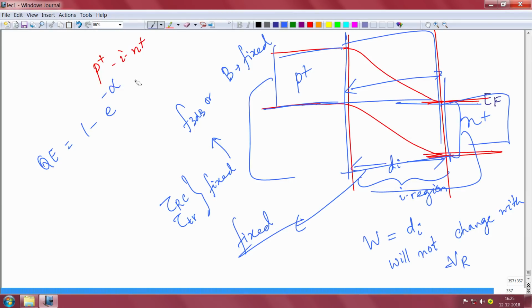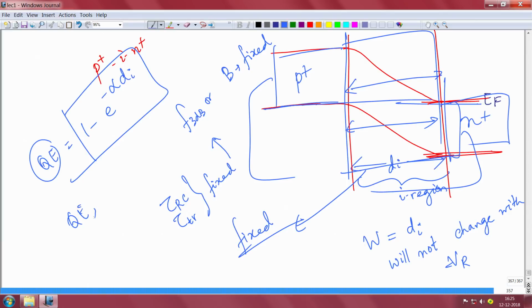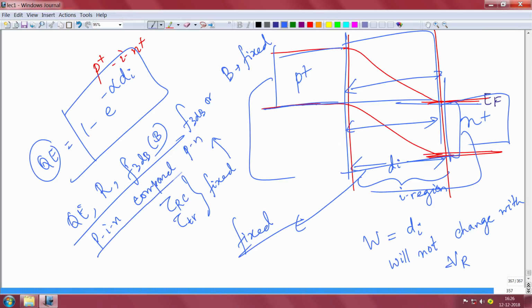So you do not know what efficiency you are going to get at minus 2 volt, minus 3 to calculate. But in PIN, depletion doesn't change. It is fixed at Wi, which is the thickness of the I region. So your efficiency can be fixed. So in terms of designing your quantum efficiency, hence responsivity, hence your 3 dB frequency and so on, speed and bandwidth and so on, your PIN device will definitely be better compared to your PN devices, because you can fix these numbers beforehand. You can design these numbers better. Okay, that's why you use that.